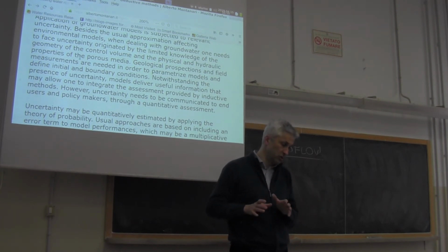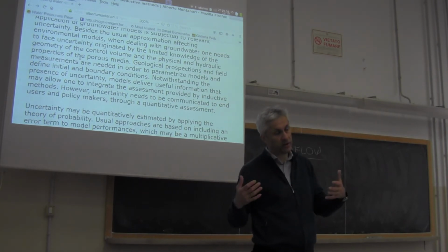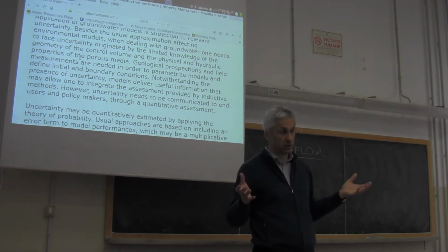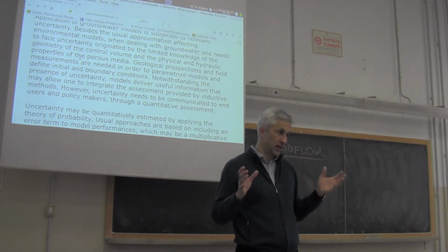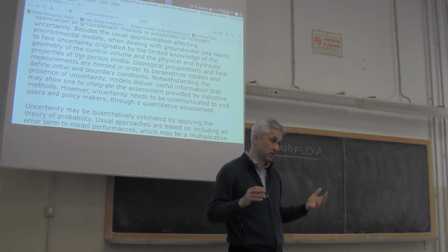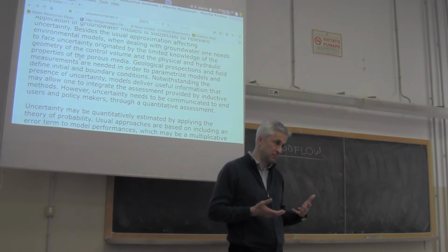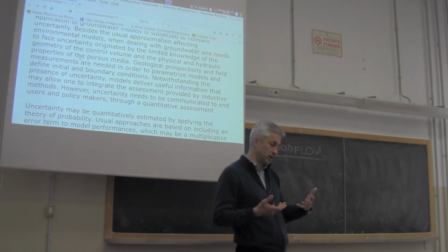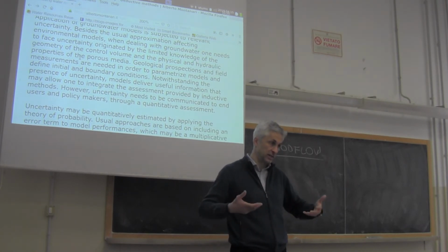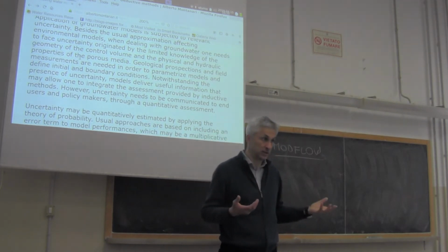So if you refer to these longer time scales, then it becomes a bit easier to quantify the inputs and outputs boundary conditions of the aquifer, and also the geometry of the aquifer can be simplified, because very fine heterogeneity, very fine details in space of the geometry are effective on the short-term changes. If we look at a spatial scale that is larger and a time scale that is larger, then the definition of the details becomes less important.